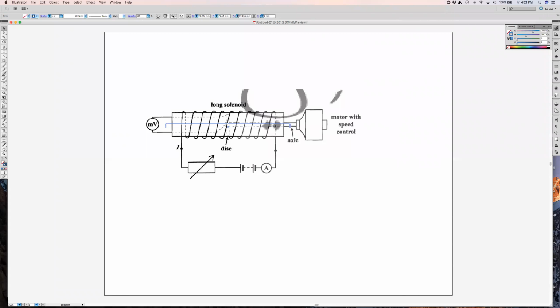Okay. All right, the rule we're using is called the right-hand grip rule. So let's apply the rule. The fingers must point in the direction of the current. The current is going up here, and therefore going up in each one of these strands. If you were to grab this, the fingers of your right hand will be pointing up, and it means the thumb of your right hand will be pointing to the left. So the North Pole is to the left. That's how the magnetic field is going to look.